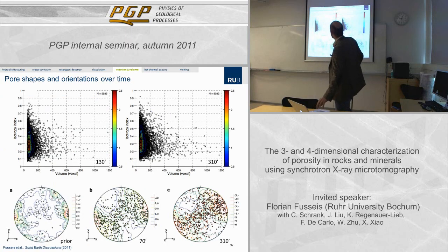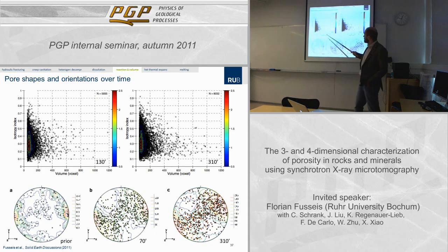What we can also show, though, is that all these analyses exclude the largest pore. They're just looking at specific samples of pores. These are the shapes, and we wanted to know, and that is relatively interesting, because if indeed hydraulic fracturing was a dominant pore-forming mechanism, then we would expect that most of the pores have aspect ratios that resemble a crack, which is generally given in the literature as around 0.1, so it's 10 times longer than it is wide. And that is a quantity that we can actually determine with our codes.